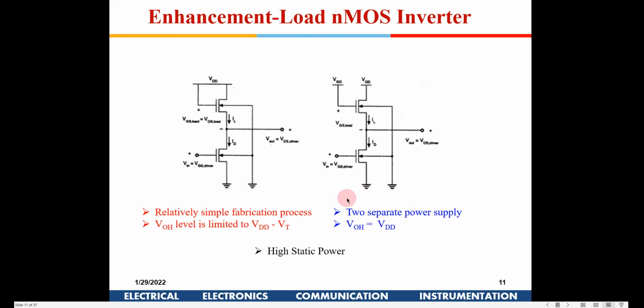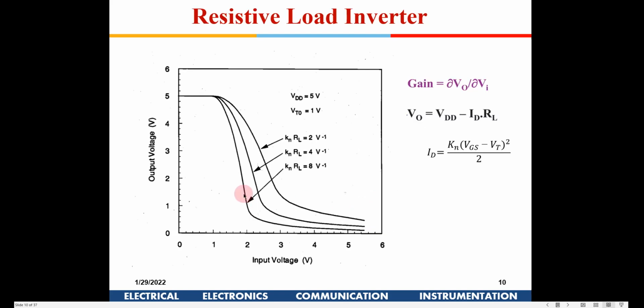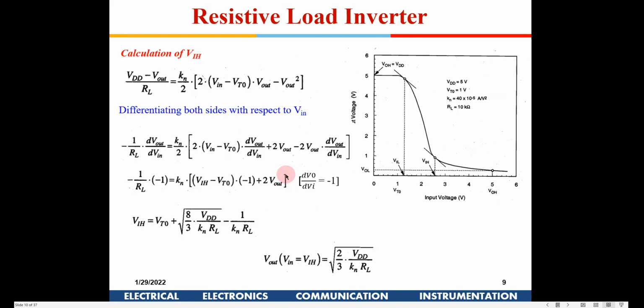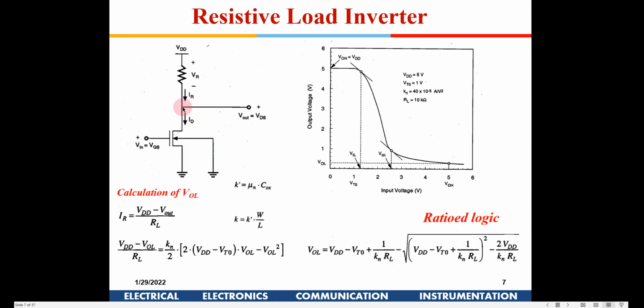So let me take on that question here. Okay, now actually if you see this transistor, when I am operating in this region, Vin is somewhere in between here. This acts like an amplifier, right? You can give a small signal here, you will get an amplified signal here. So you can use it as an analog amplifier. Okay, and the gain in that amplifier will be defined by the slope of this curve, delta Vout by delta Vin. So that is the significance of gain there.